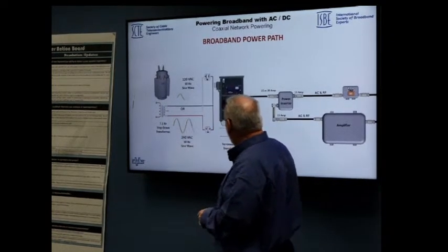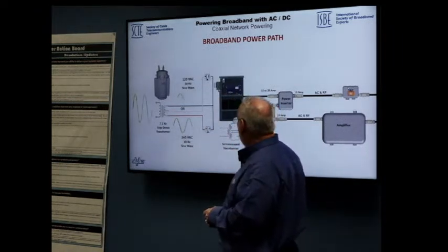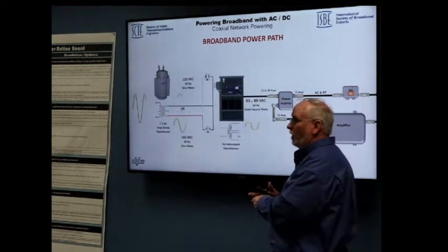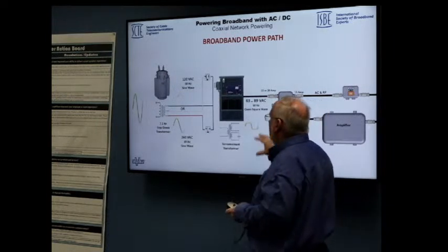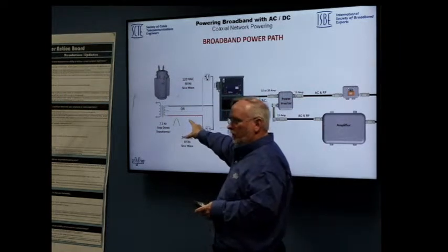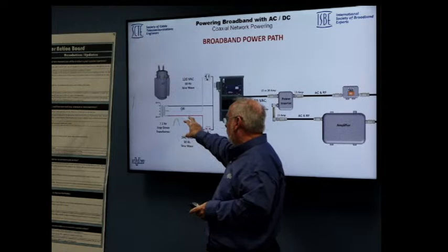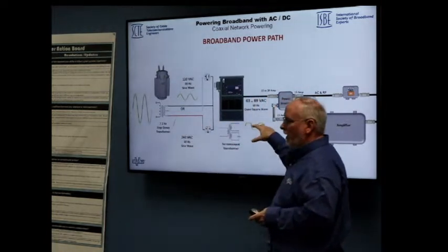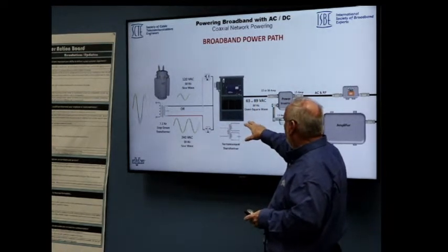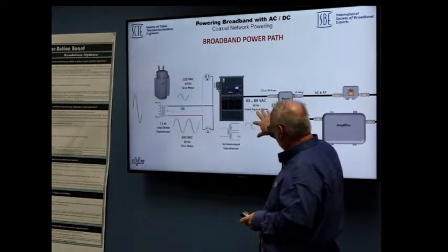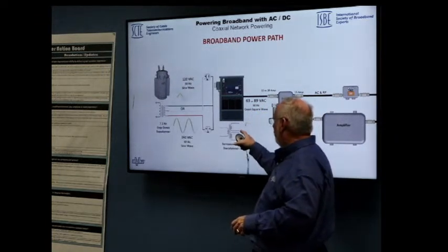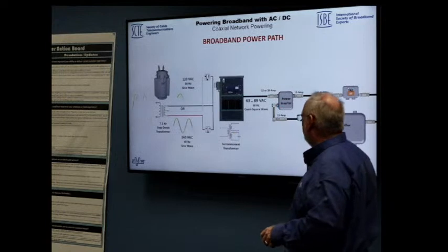Then inside here, there's a ferroresonant transformer. That's the tank circuit, right? So we output 63 or 89 volts in what we call a trapezoidal wave or quasi-square wave. The interesting part is, because of the sinusoidal nature, a sine wave has 0.707 captured energy when you look at your RMS versus your peak. This is way higher than that. Depending on the power supply, it can be up in the 90s. What we're doing is creating more energy delivered at the peak, so there's a lot of energy in here versus what it would look like if the same voltage in a sinusoidal were represented.